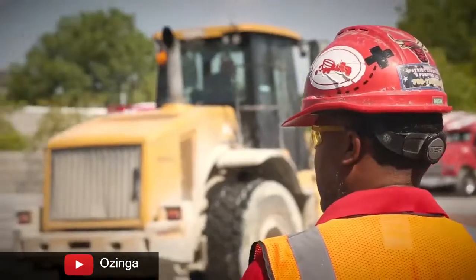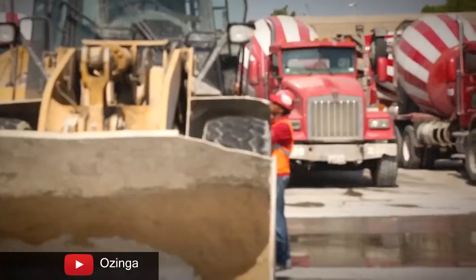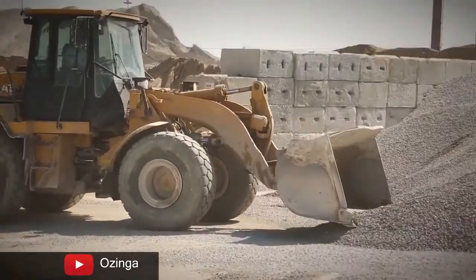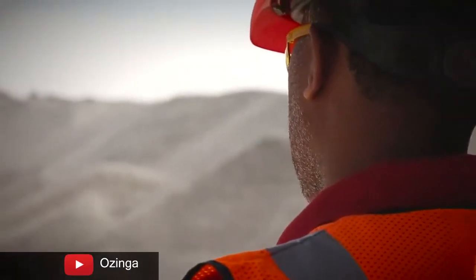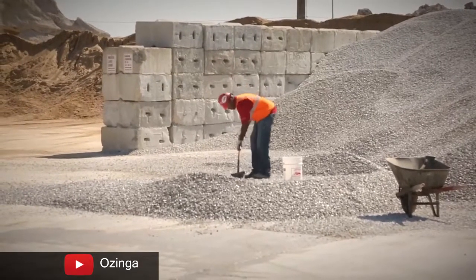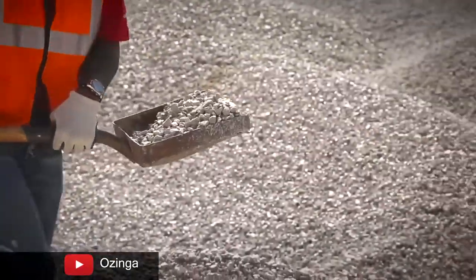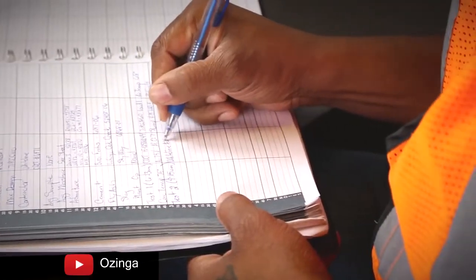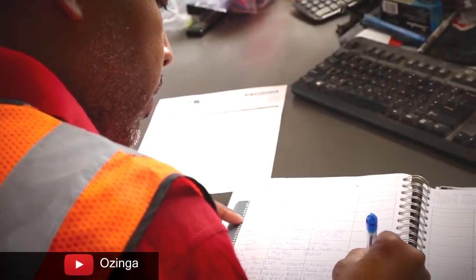A typical day on the job is early mornings, an hour before the first load goes out. Grab some moistures, which are the stone and sand, and we're trying to see how much water is within that aggregate. Then we start looking through all the orders, making sure that the orders are set up to the way that the mix should be. Then the trucks come. Then now it's time for the actual testing.